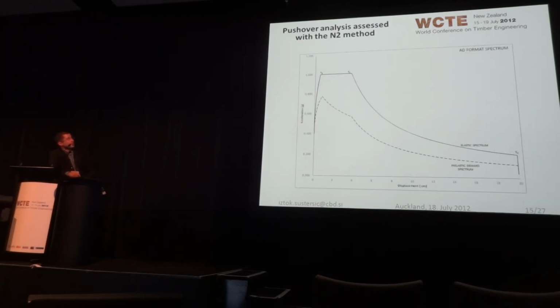What does that mean? You have the elastic spectrum and the inelastic demand spectrum. The difference between the two is the reduction factor, which is based on building ductility and vibration period. Buildings that have short vibration periods are very prone to hysteresis response.